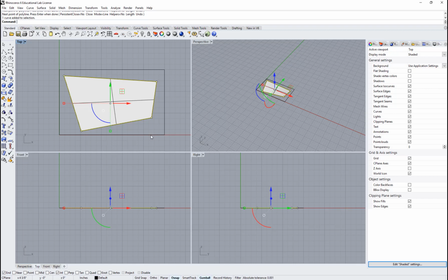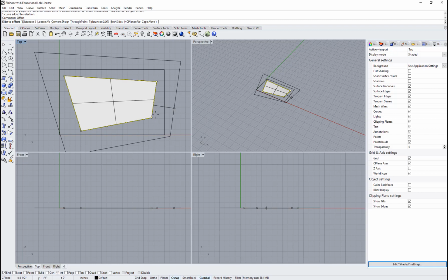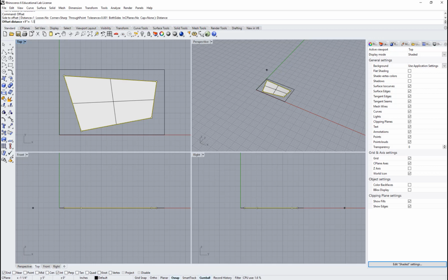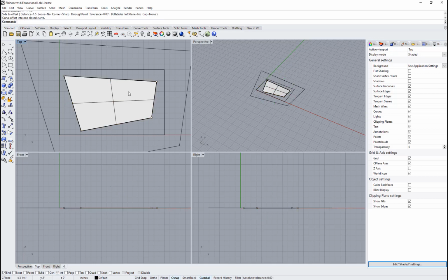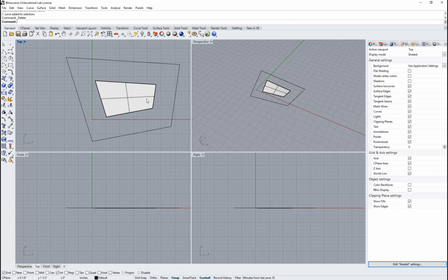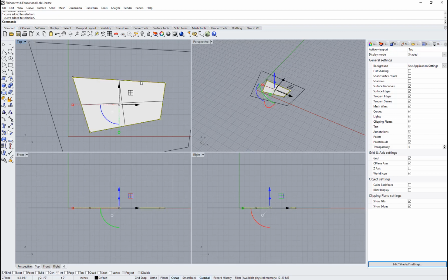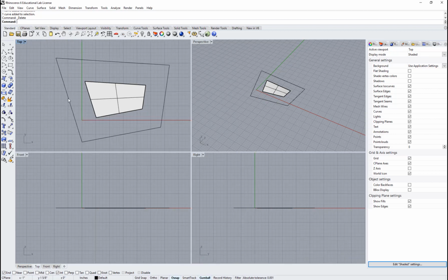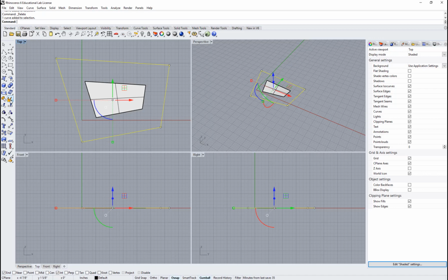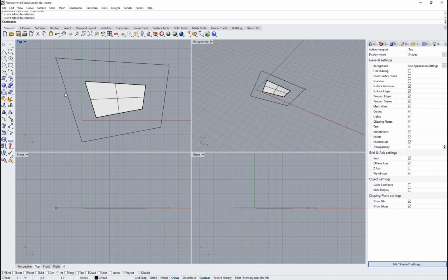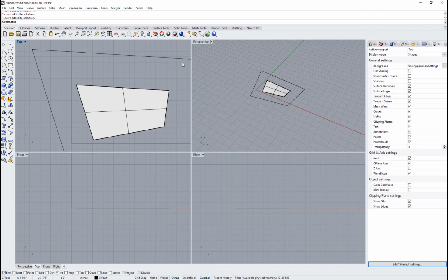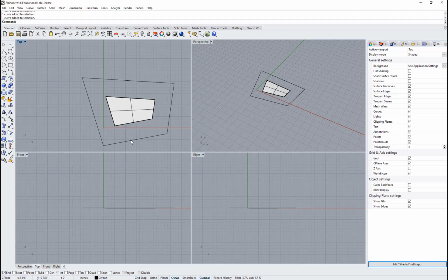I'm going to offset the shape that I made, and I'm going to turn this into, let's see, maybe 1.5. 1.5, enter, and there it is. Since I don't need this, get rid of that. I don't really need this shape right there. Get rid of that perimeter line that I made. From this, I am going to explode this object, because again, this is just a guideline for me to work around, so I know about how big to make the side surfaces.